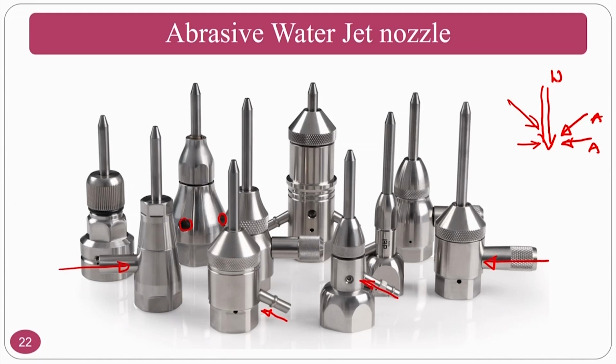Okay. This is the water jet which is coming, and abrasives, how you can feed the abrasives. Okay. So, if you feed against the flow, normally the jet velocity may change drastically. For that purpose you should look into it, maybe the mixing may be better. Okay. So, you can compromise on the mixing ability as well as the velocity and other things you can work out.